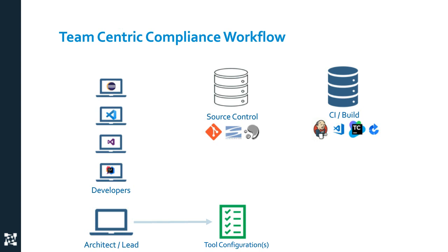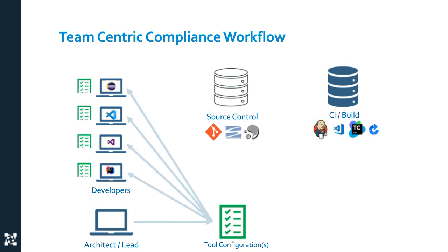standard, MISRA, AUTOSAR, CWE, CERT, for example. Those test configurations or those tool configurations that control what checkers are enabled, how they're parameterized, how they're configured, how they map to the specific standards, are then shared across the development team.